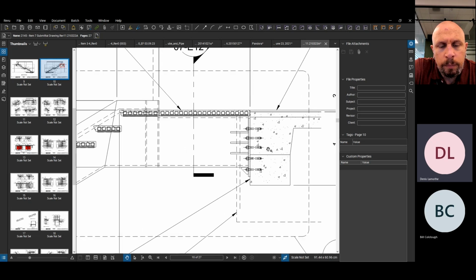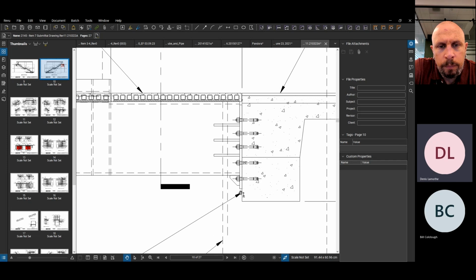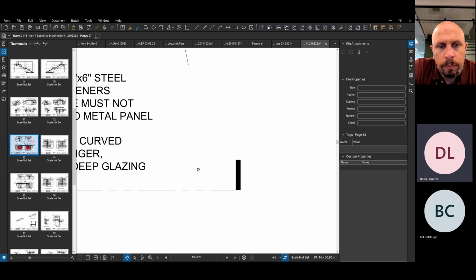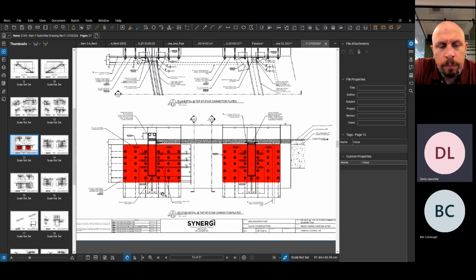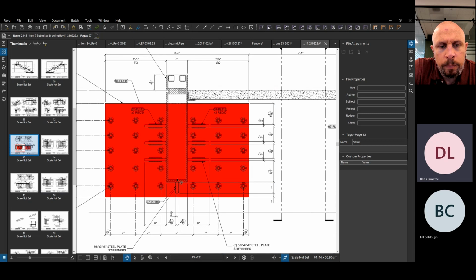We were able to utilize a big base plate, or a big plate attachment, that was pre-welded to the stair stringer, and then we just went in there with a lot of anchors to bolt into the concrete slab. Your plates ended up looking something like that for each stringer. You can just see the quantity of anchors that we had in there for this particular condition.